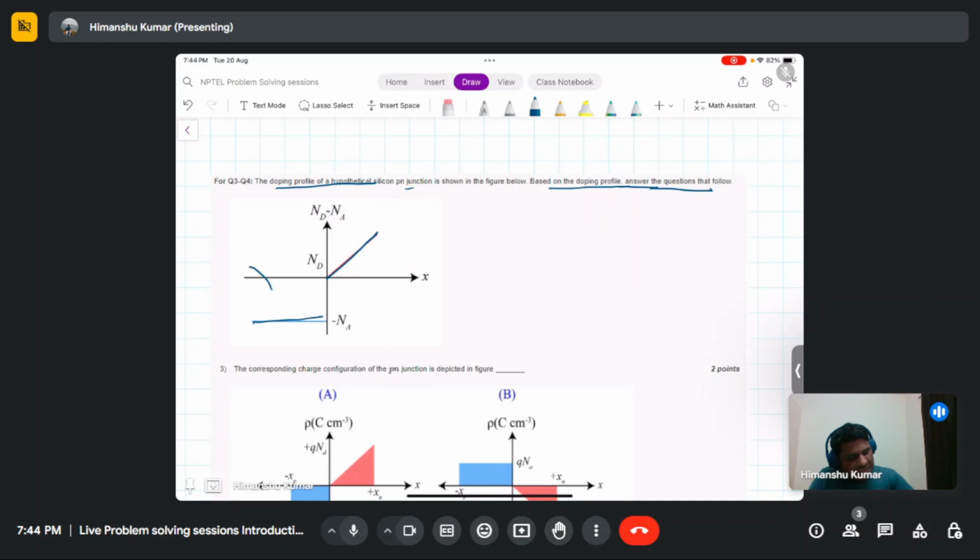So this side is the uniform doping case. If you dope all the acceptor atoms uniformly, then that is the case. And this side it's linearly graded, so it's a linearly increasing doping profile. So this side, if you plot the charge, it is like